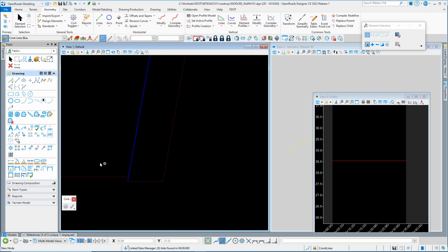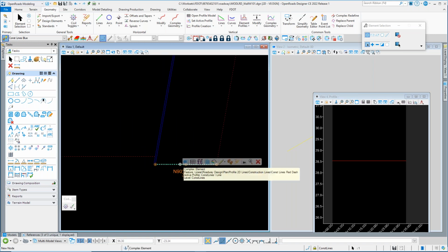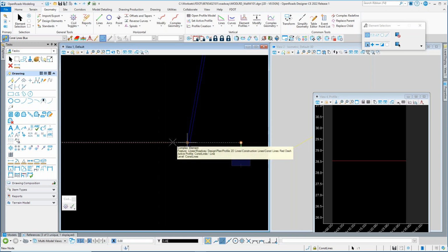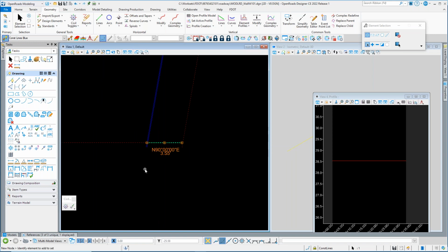All right, now the next thing we want to do is move these sides in so that they match these guys. So using AccuDraw again, I'm just going to grab that manipulator and move it up. I'll lock it out with the AccuDraw lock, and I'm going to just snap to that other side.